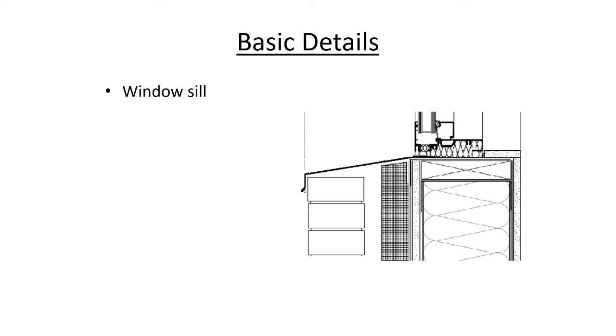Moving down to the sill of the window, we see the details that are required to make sure that the continuity of the air-water barrier is maintained. You'll notice in this case that we've used wood blocking to wrap around the punched opening and tie into the cold-formed steel framing. Some contractors prefer this type of application, as they feel it's easier to install the windows. It basically is an option as far as I am concerned.